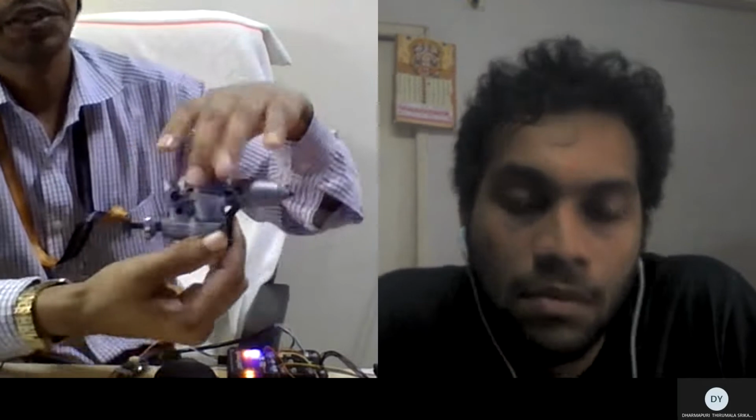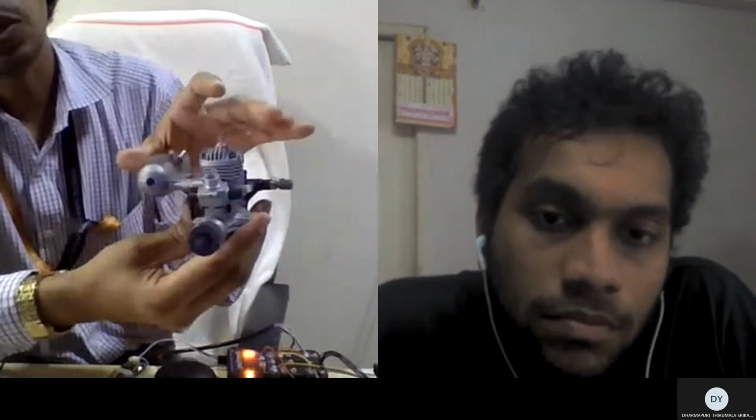And for an integrated drive generator, what do we need? Your RPM variations are required based on the aircraft need, correct? So what is the main target there? Constant speed. The RPM varies based on your power requirement and thrust requirement, but the generator always requires a constant speed. Only then can it generate that particular frequency.